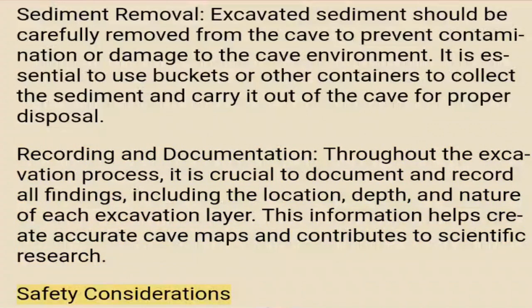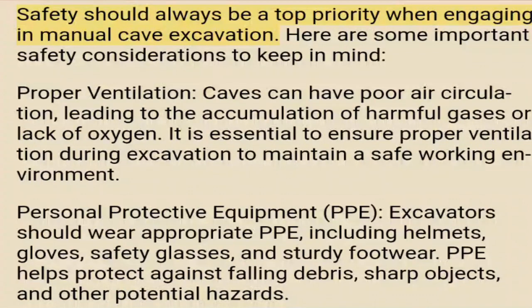Safety considerations. Safety should always be a top priority when engaging in manual cave excavation. Here are some important safety considerations to keep in mind. Proper ventilation. Caves can have poor air circulation, leading to the accumulation of harmful gases or lack of oxygen. It is essential to ensure proper ventilation during excavation to maintain a safe working environment. Personal protective equipment (PPE). Excavators should wear appropriate PPE, including helmets, gloves, safety glasses, and sturdy footwear. PPE helps protect against falling debris, sharp objects, and other potential hazards.